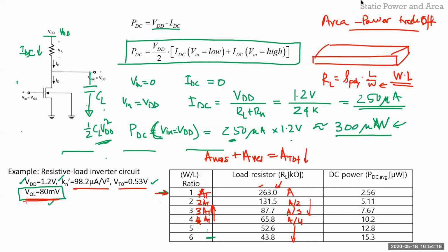So your question was, how do we choose? Well, it depends on your application. If your application is absolutely power sensitive, for example you're designing an IoT sensor node, and your entire IoT sensor node is supposed to run on a coin battery cell for 5 years, there you're ready to spend more area to consume as little power as possible.